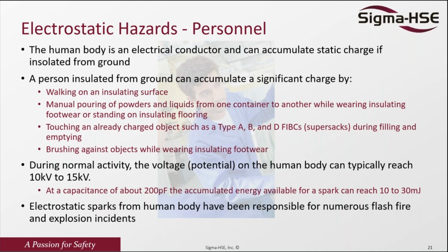And that is very, very common in industry, maybe powder in the pharmaceutical, in the ink industry, where they handle both flammable solvent or maybe powder. And in this case, a flammable mixture could be formed inside the container. However, during dumping, if you are not grounded, charge is being generated.